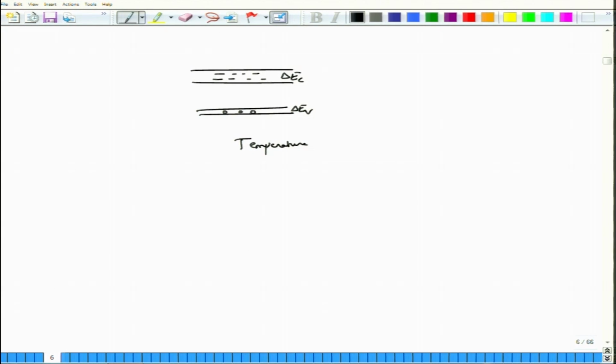Okay, so as we increase these numbers, we increase the chances that optical signals can be absorbed, and the carrier density can increase in the conduction and the valence band. Actually, there are two things that are going to happen, right. Once the energy comes in, and if we have already created a number of electrons in the conduction band and holes in the valence band, the electrons which are there have actually pushed down. So these are the electrons which are not participating in the conduction, whereas the holes are there.